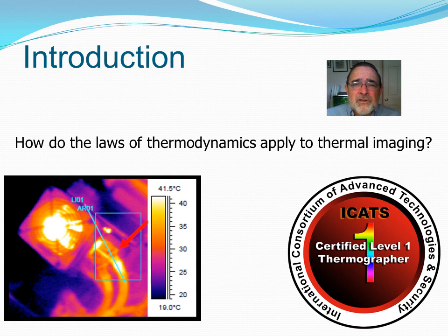This is in an air-conditioned space, and so nothing seems hot as you walk past. You don't feel the radiation coming off of this device, but the infrared thermal imaging device can see it. We can spot this problem, and this problem was immediately repaired because of the high priority and importance of this piece of equipment. In this space, there were a number of these that were corrected immediately. But what is the issue?